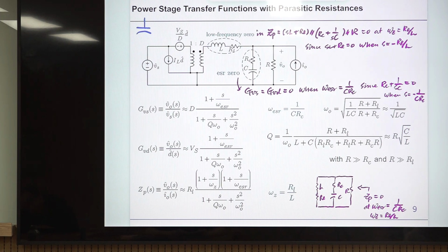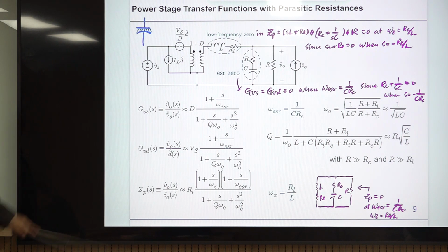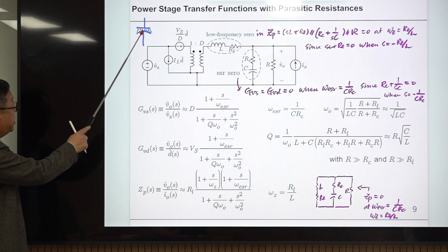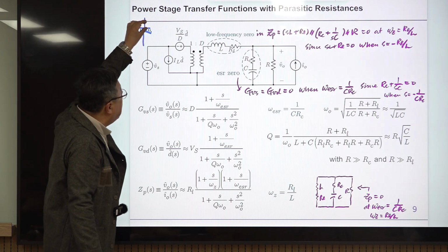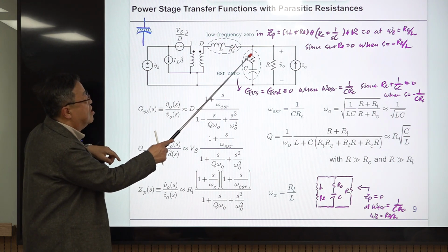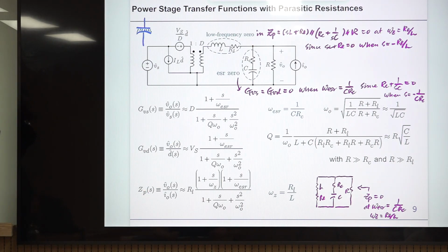It has two parallel plates and it is filled with some dielectric material. So if everything is ideal, then this has only capacitance, but this material is not ideal. This dielectric material is something less than ideal. There is some resistive component coming in. The resistor inside of this material is taken out of here. Okay? And it is represented like this.